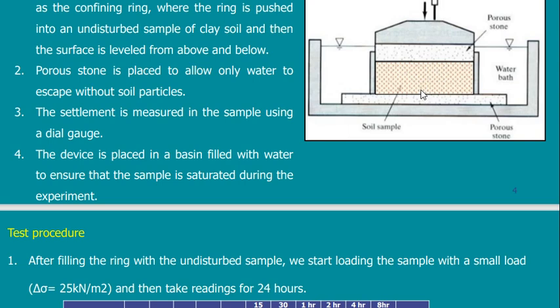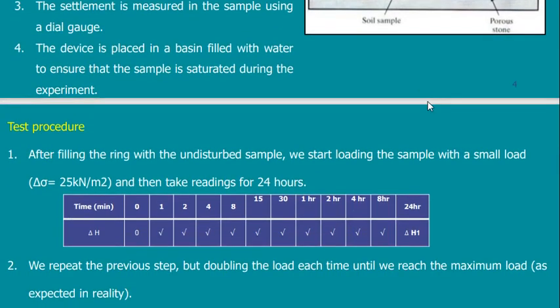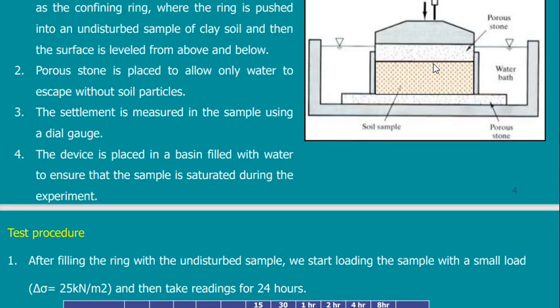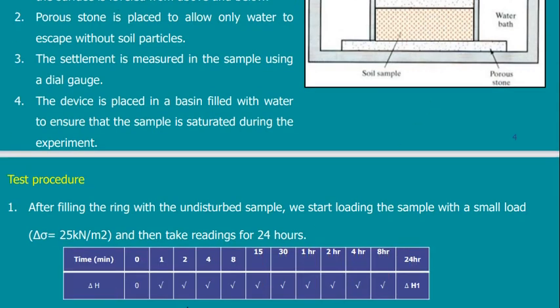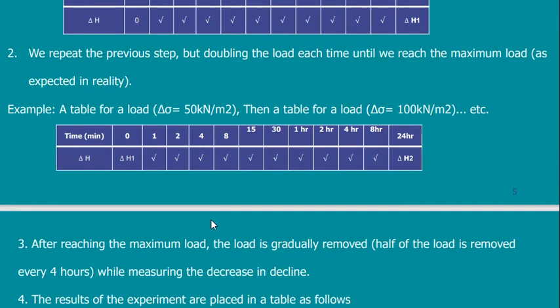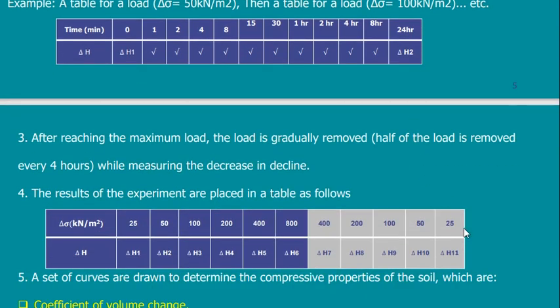But suppose it is clay, then the water has to leave this sample. So with time, the water will leave the sample and the sample will start to settle. So this is what we do in the lab. We just put the load, put everything on top, and then just record the settlement that is happening maybe after 1 hour, 2 hours, 8 hours, and so on, till I reach maybe 24 hours or maybe a few days, and so on.